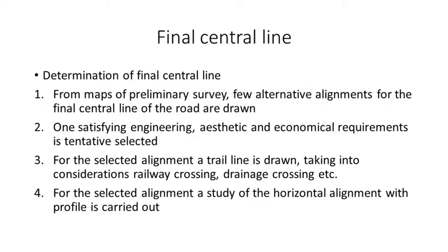First one is the topography of the area. Next, the length of the route. Next, what terrain condition, soil condition, gradient, and curves. Next, we require the data of the geology of that area. What is the nature of that hilly slope? Next, we require the information of climatic condition. What is the maximum and minimum temperature? How much is the rainfall intensity, snowfall?